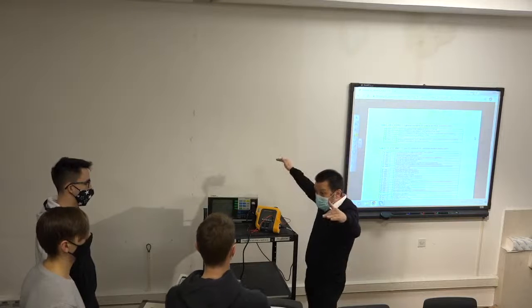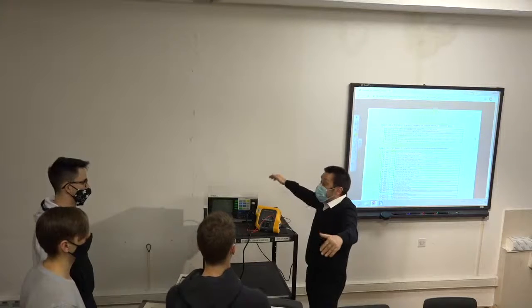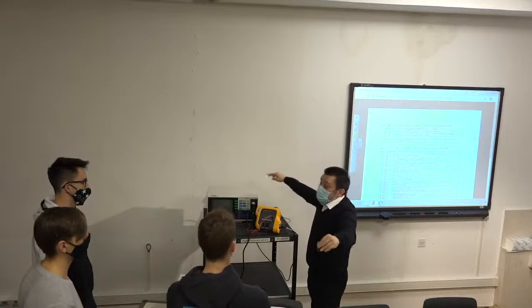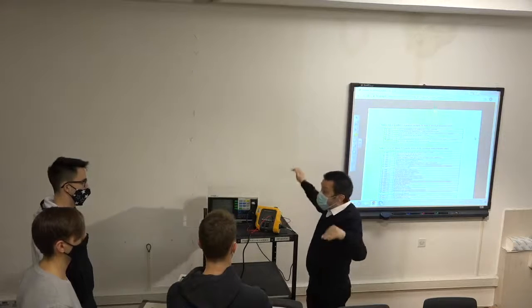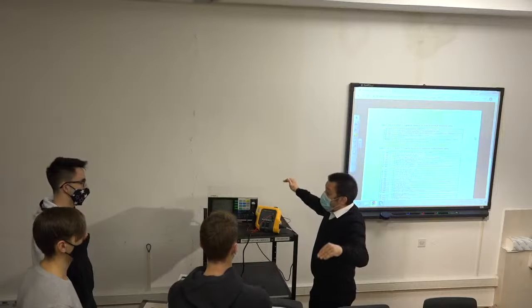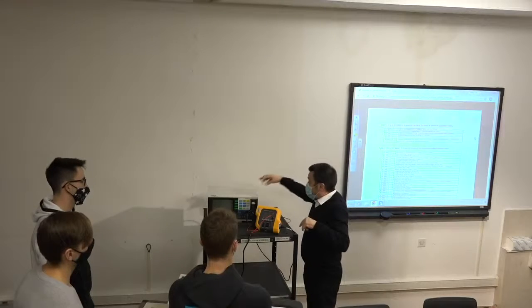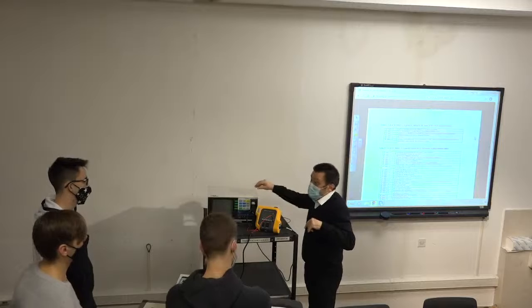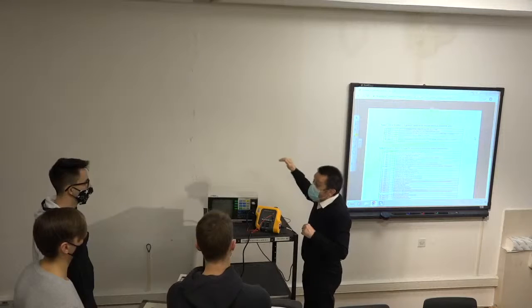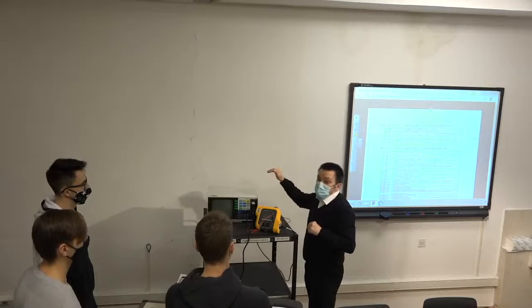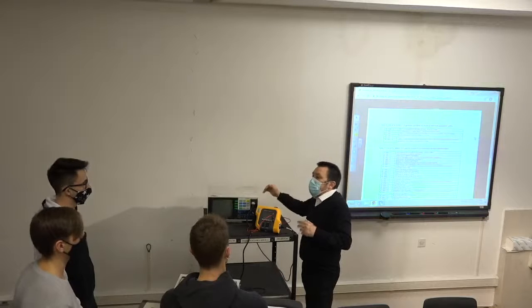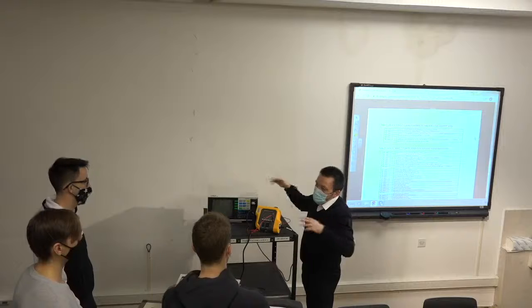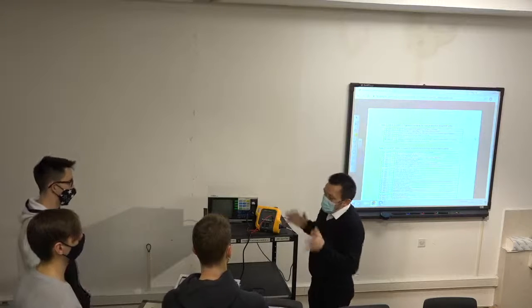On this path, the voltage that rises because of all the collected current might be high enough that at the point where you touch a device or your house appliance, it might be higher than allowed by the standards, and that means it's considered to be dangerous for your heart or for burns or whatsoever.